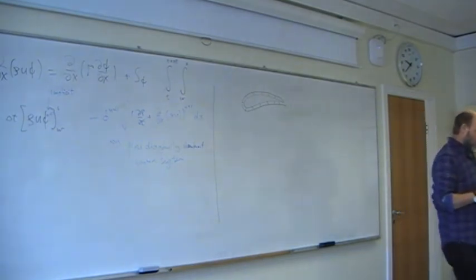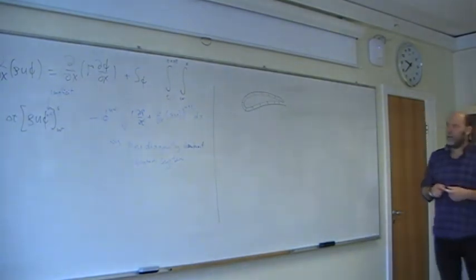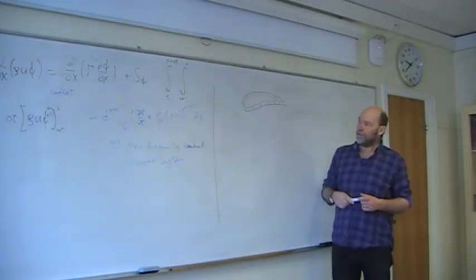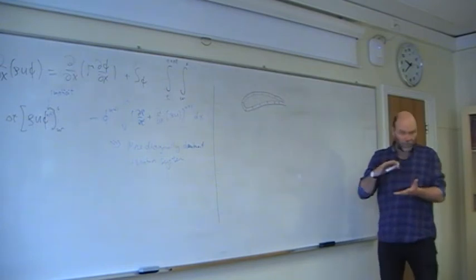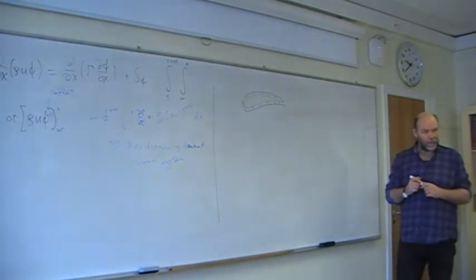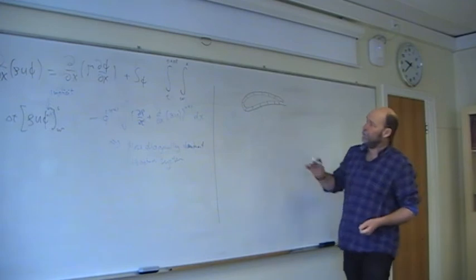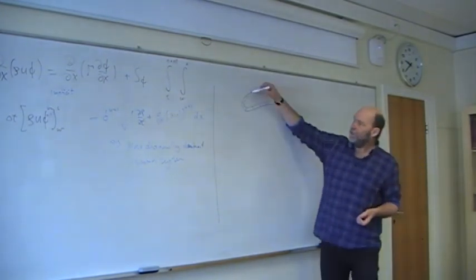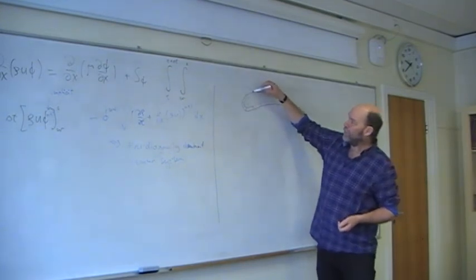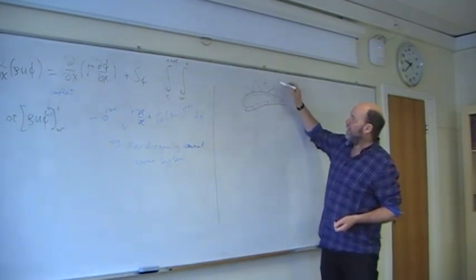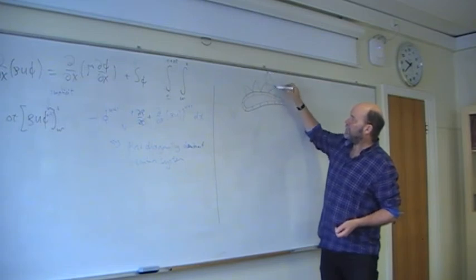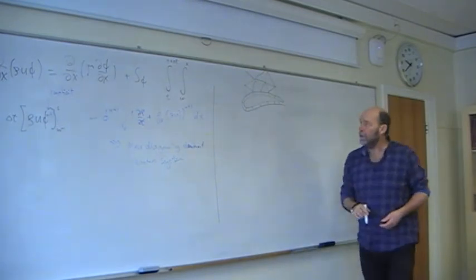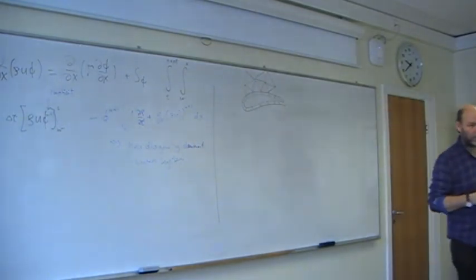Can be 5, 6, 10 cells thick, but you have a rectangular, more or less, structured grid system close to your boundary. Very good idea. And then outside, you are not so worried about the solution, it doesn't have to be too accurate. So now you can start using unstructured meshes, for instance, and making bigger and bigger cells to find a solution.